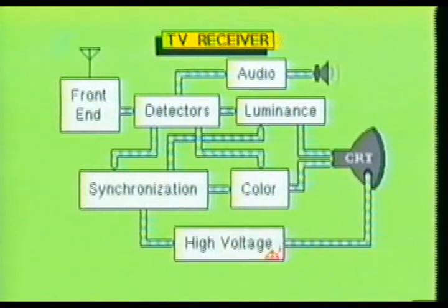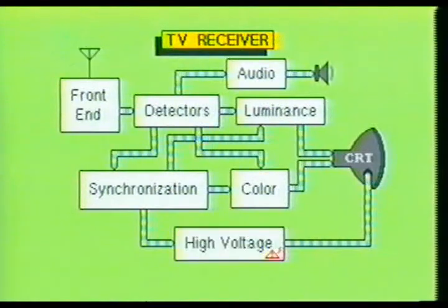The high voltage section is responsible for providing the high DC potential required to operate the cathode ray tube. Extreme caution must be maintained when troubleshooting on or around this lethal circuitry. Voltage levels as high as 35,000 volts may be present in these stages. Specially designed test equipment is required when working in the high voltage circuits.